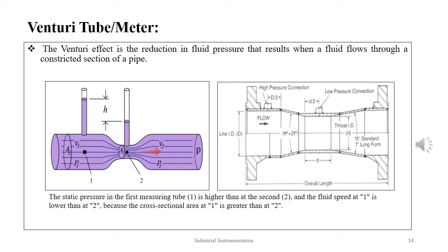In Venturi, the restricting element is a tapered tube instead of a sharp edge orifice. The tube gives a smoother velocity change which results in a small permanent pressure loss to approximately only 10% of the differential pressure measurement. The tapering edge at the input side ranges somewhere between 19 and 23 degrees, and at the outlet it ranges somewhere between 7 and 15 degrees.